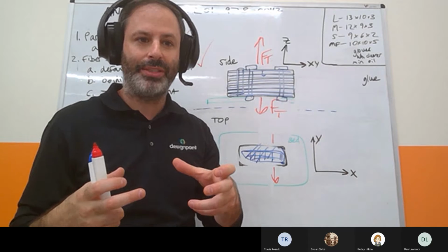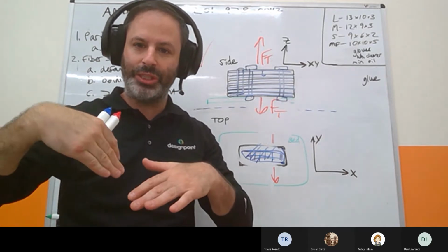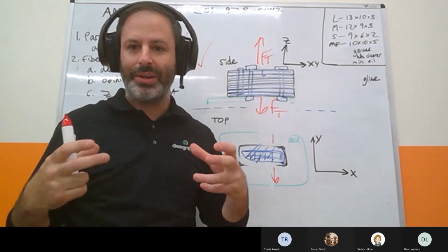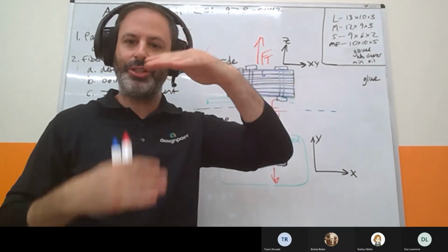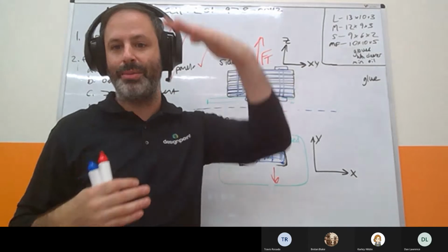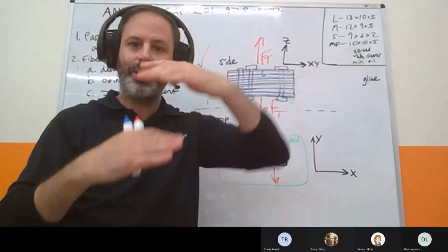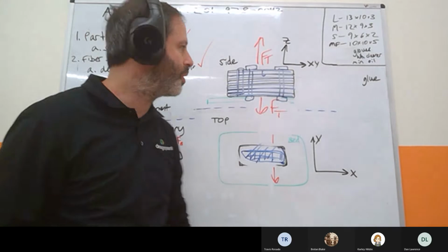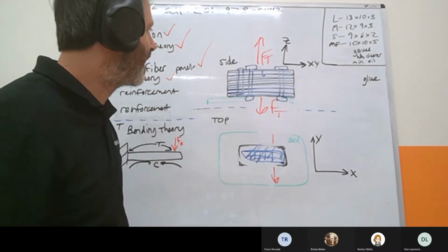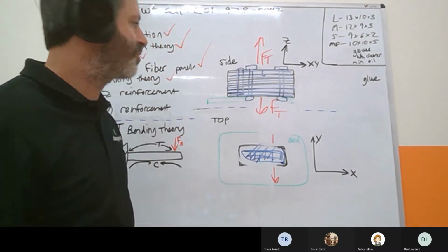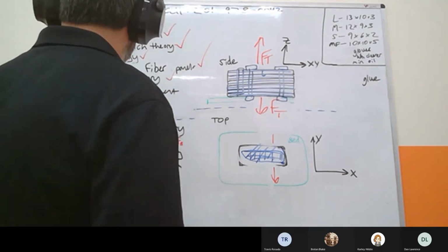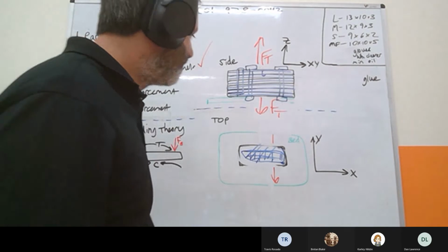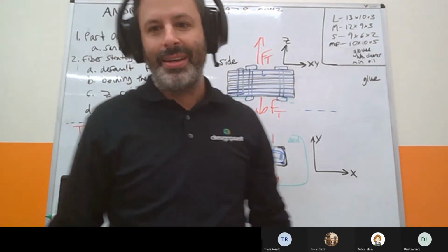And we talked about, for a Z force, using these fiber panels on the extremities, and building from the extremities. If you need to add more strength, you could add multiple panels, but build from the extremities. And we also talked about compressive loads. We talked about stacking fiber, using bolts for reinforcement, and using dowels for shear force. So I think that's it for the session today.